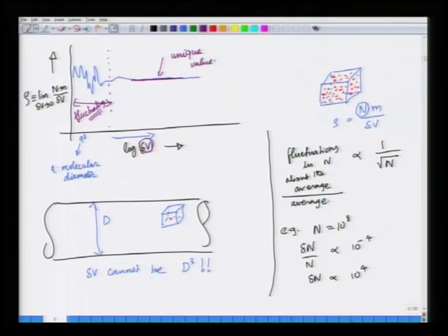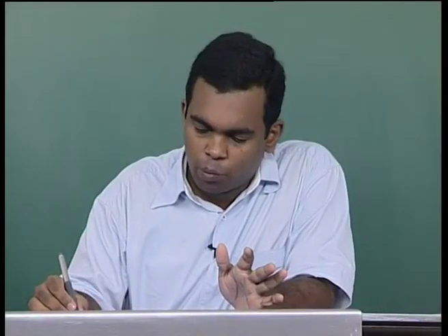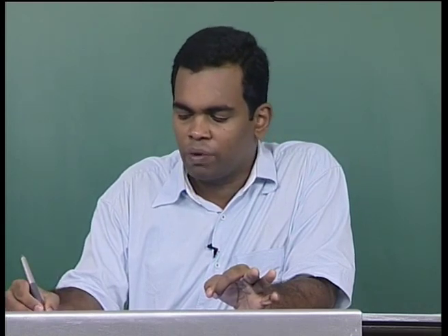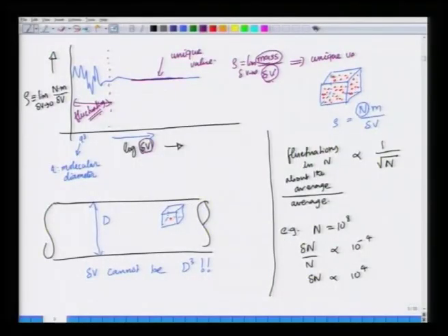That is, density is the mass present in that tiny volume divided by the volume. So, it is defined as the limit as delta V goes to 0 of mass divided by volume. As you shrink the volume such that it is still large compared to the molecular scales, the mass that is present in that volume will also decrease, but the ratio of these two will approach a unique value, that is the continuum density. Okay, this is the density as defined in the continuum approximation.